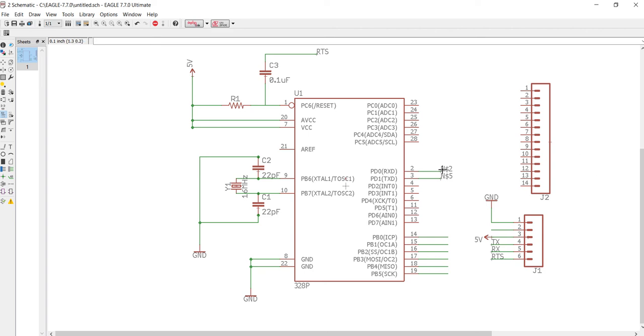So I'm actually going to flip this. I want my receive here, RX, to connect to the TX on this side. So I'm actually going to label this TX because I want it connected to this TX line. All right, so even though it looks like I've made a mistake and misnamed this, I haven't, because I want these flipped. So the RX is connected to TX, TX to RX. All right. We're going to leave this pin empty, and why don't I just delete that to make sure I haven't made any mistakes there. And then